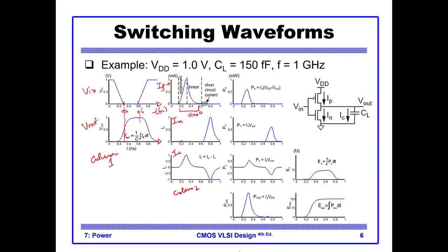So that's why the PMOS current goes up to the saturation point, and then when the capacitor CL is fully charged, from that point VGS minus Vt drops and it goes to the linear region. So this is the current of the PMOS.